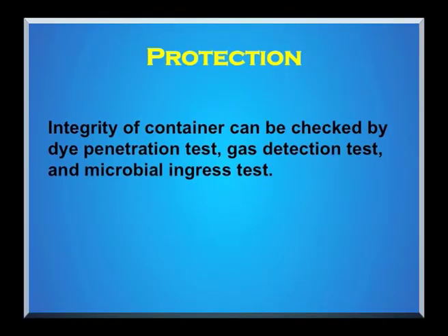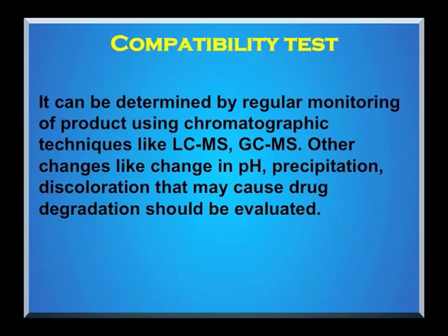Another important test is protection. When a container is anticipated to offer light protection, or is a light resistant container, it must meet the light transmission test specified in the monograph. The integrity of the container can be checked by dye penetration test, gas detection test and microbial ingress test. Another very important test is the compatibility test.